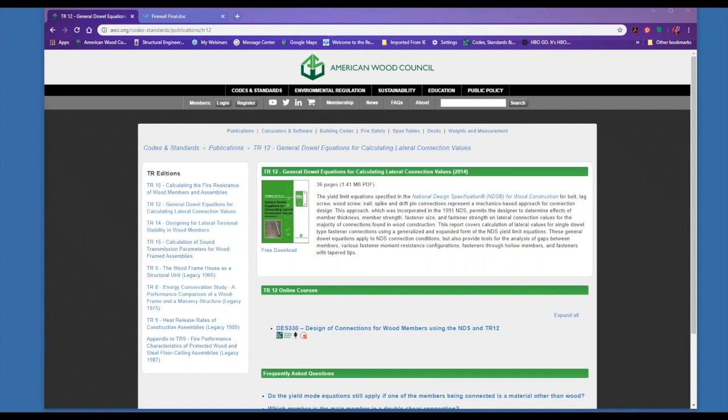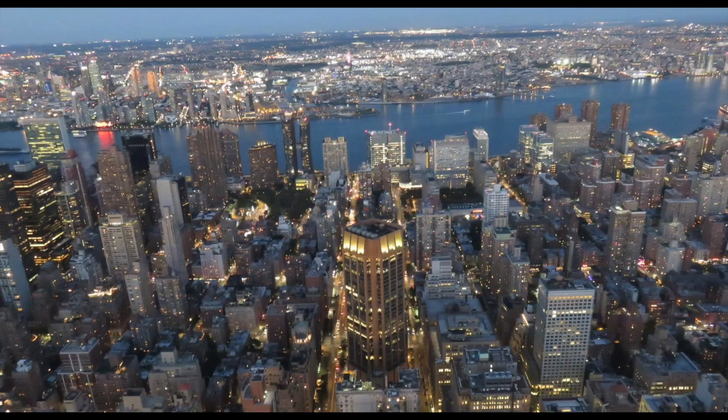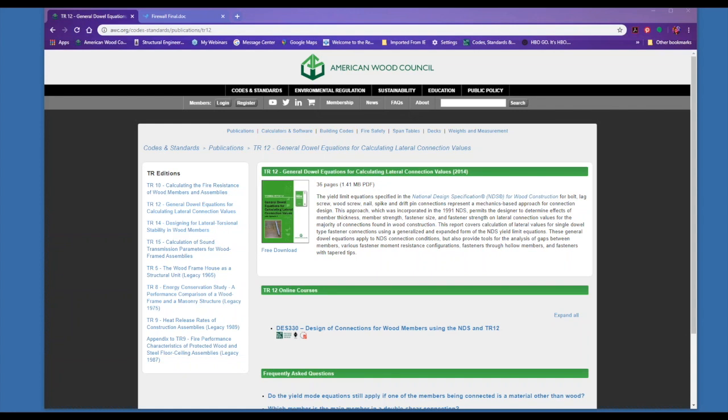If you are in a shear load, where the load is applied perpendicular to the length of the fastener, you're only going to use half of the length of the tapered tip. And going back to that technical report 12, TR12, there is a whole boatload of calculus and analysis in Technical Report 12 that shows that that assumption of just using half the tip length gets you to within 1% of an exact algebraic solution that assumes a function across the sloping